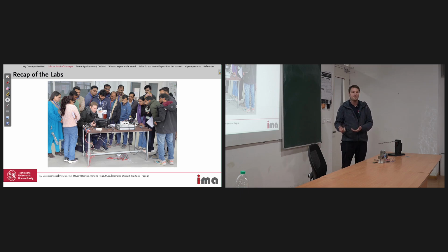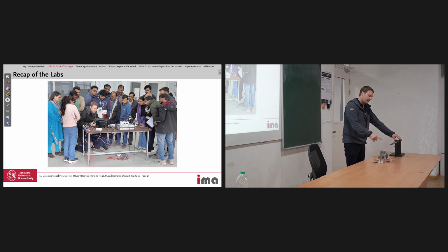And if you do it for yourself, then sometimes it makes a lot of sense to put another sensor on the clamping or on the desk even. So we had some experiments on a simplified wing model, where we had a sensor here on the table and the wing here on the table, and everything was massive steel. But anyway, then we got some really terrible noise and we couldn't identify why. And then we had to look at the table, and then it was clear that some vibrations went through the table into the sensor. So what we then did is